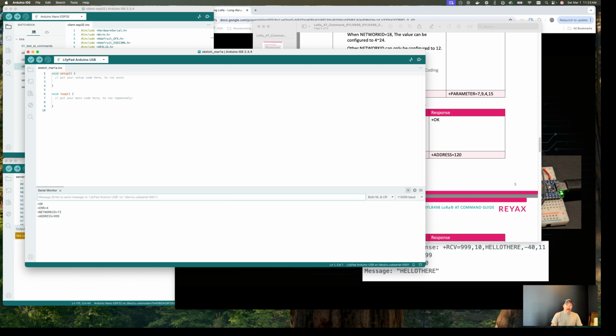All right, I'll leave it as is. No, I'll show you. So let's change the address. So let's do AT plus, and now this is my radio's address, not my destination address. It's my radio's address, and I'm going to change it to 101, for example. And I get back okay.